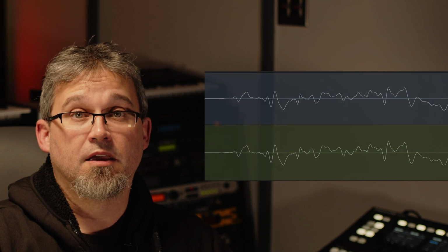Multiple manufacturers claim that increased impedance affects the sharpness of the transient. The claim is that lower impedances smear or flatten the transient. This is a really easy one to check out, so to do so, we popped our 121 in front of our studio monitors and recorded the playback of a snare hit. First we set the impedance to 150 ohms, and then we set the impedance to 15K.